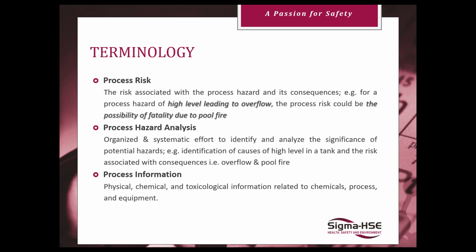But if it's a chemical containment bund around storage tanks and you have an overflow there, now you're looking at, all right, is there the possibility of personnel exposure from this? If it's a flammable material, could we now have a pool fire because we have this flammable material sitting there? So you look at what your process hazard is, what its consequence is, and that'll give you your risk.